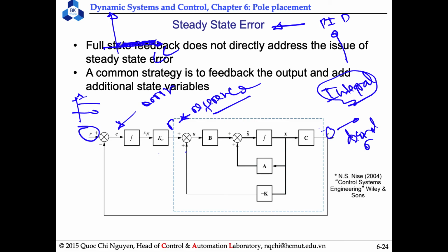If it is very small, this cannot drive the system, but it accumulates until, after some time, it becomes big, and this can drive the system. This is the role of the integral here, and we do the same strategy here.